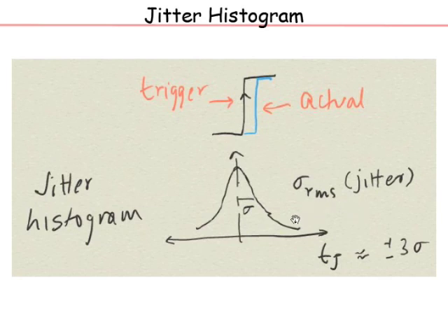Now when you budget, say you're looking at the cycle to cycle and you look back to your timing analysis, say the launching clock was here and the arriving clock happened maybe a little earlier. So you might have to budget for some multiple of sigma as the timing jitter, maybe plus minus 3 sigma, or T jitter maybe 3 sigma or 6 sigma.